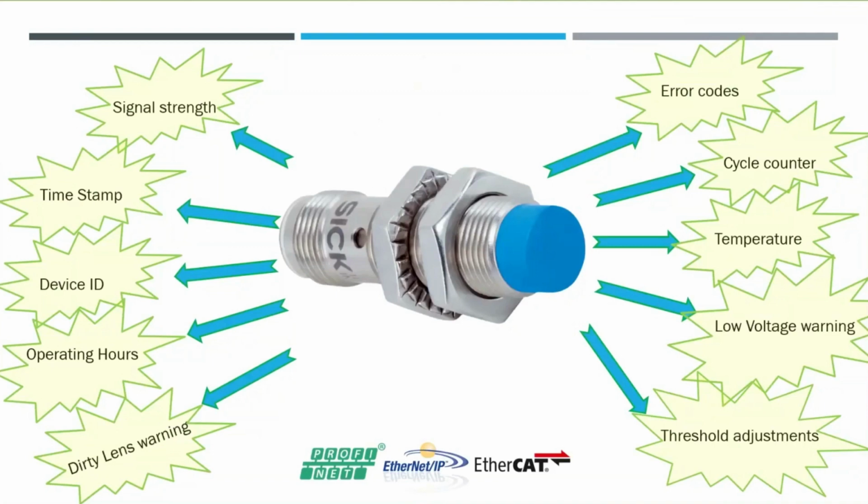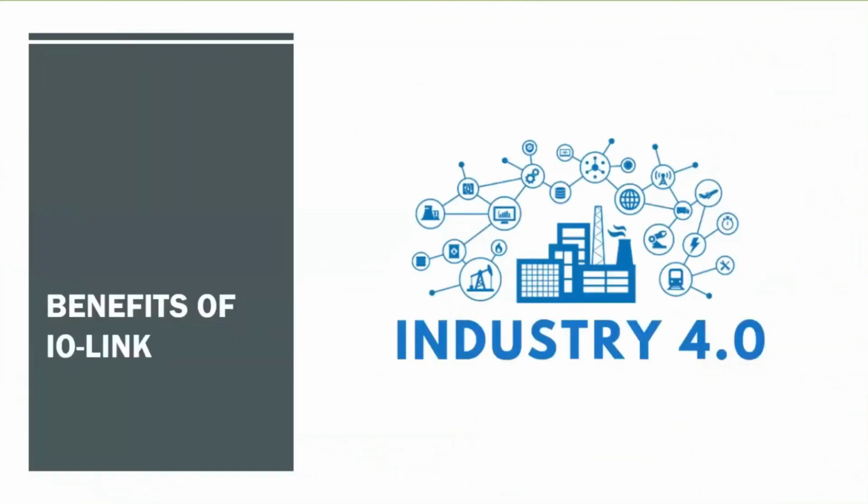In this case, it makes more sense to have a distributed system. What if you can actually have something that can distribute the cost of the whole system on it? And here IO-Link master blocks come, where you can actually have 8 sensors connected on that same master block, and you can still bring it on the field bus level protocols. And this way you are actually distributing the cost. And that is the power of IO-Link. So obviously the very first benefit of IO-Link is that you are Industry 4.0 ready, or industrial IoT is supported by your facilities.